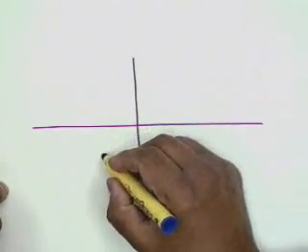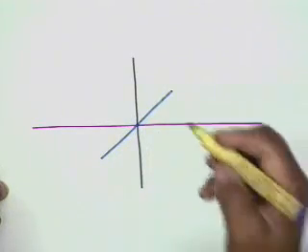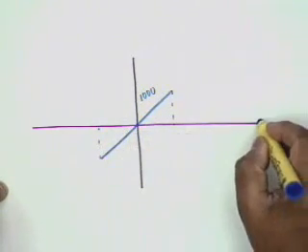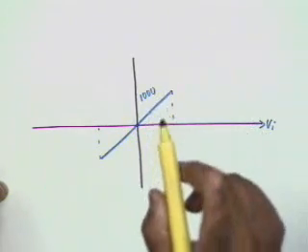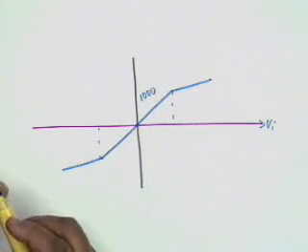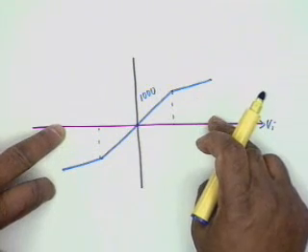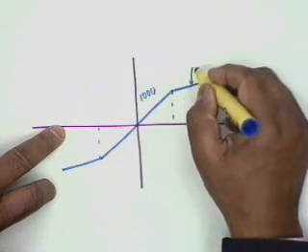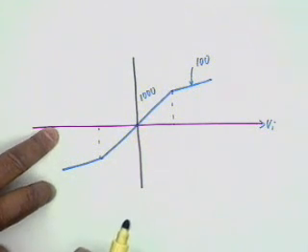However, make an approximation to this characteristic through piecewise linear curves. Let's say you have this as the linear region, and suppose the gain here is 1000. As soon as you exceed the dynamic range, the curve tends to saturate. If you approximate that by a piecewise linear curve, let's say the curve goes like this. Obviously, if the input range goes right up to here and here, there will be a lot of nonlinear distortion because of this kink in the gain curve. Let's say the gain here is 100. Now let's see what happens with negative feedback.